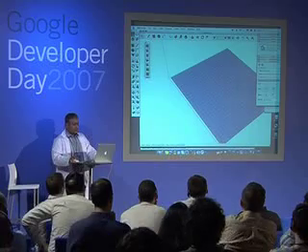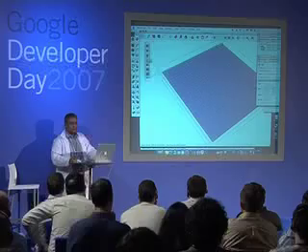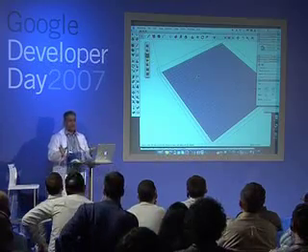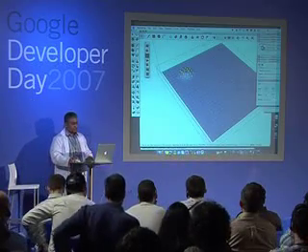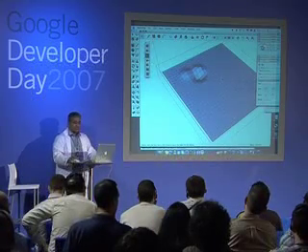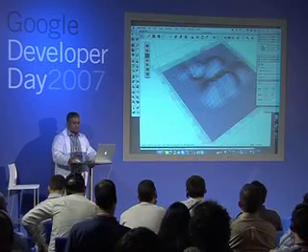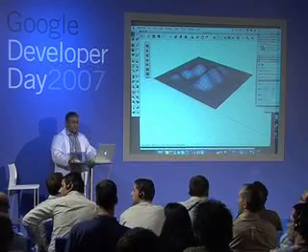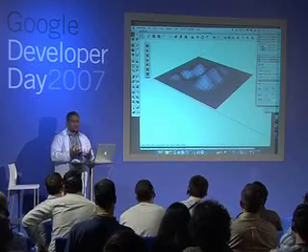Okay, now it's an object, so I'm working inside that object, and we now have this smooth tool. This has a radius, a diameter of the area that we are going to now start creating the shapes. At the moment, it's roughly 9 meters, so I can select that and start pulling the shape. I can change that to 15 meters, make it bigger. And start creating terrain. But this surface, you can see all these little squares on them.